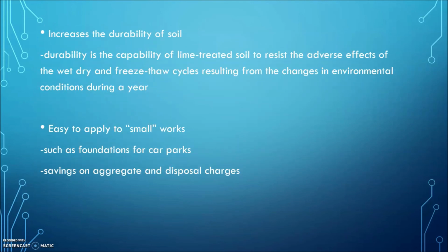The lime treatment will also increase the durability of soil. Durability is the capability of lime-treated soil to resist the adverse effects of the wet-dry and freeze-thaw cycles resulting from the changes in environmental conditions during a year. Next, lime treatment is easy to apply to small works, such as foundations for car parks, and makes savings on aggregate and disposal charges.